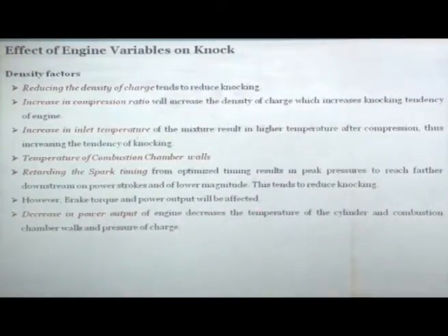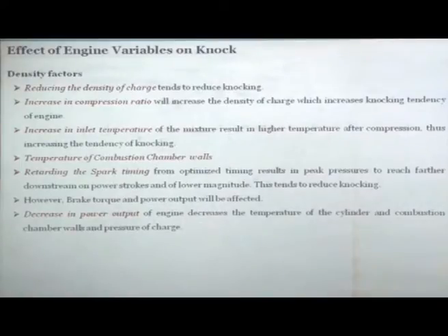A decrease in power output of the engine decreases the temperature of the cylinder and combustion chamber walls and the pressure of the charge. So at lower loads, the engine will have lower tendency to knock. At higher loads, the engine will have more tendency to knock. Okay, this reduces the mixture and end gas temperature, which reduces the tendency to knock.